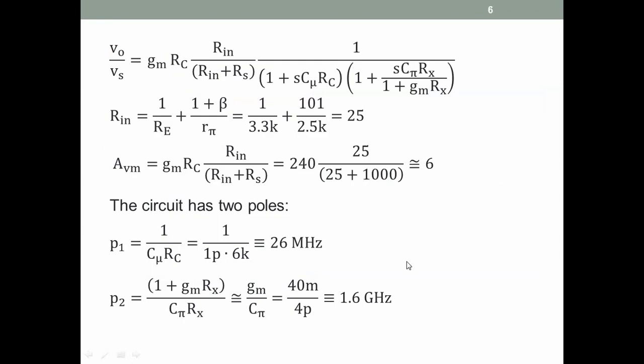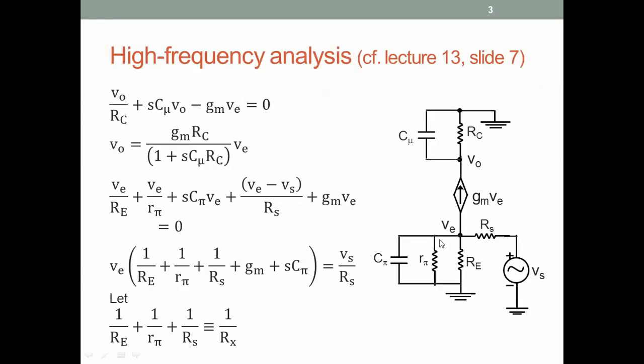So let's go back to the circuit. I mentioned this just a little while ago. There is no capacitance between the input and output of the common base amplifier because of the construction of the bipolar transistor, and because there is no Miller capacitor, there is no Miller effect experienced by the common base amplifier, and therefore the poles of the common base amplifier, the dominant pole, are at much higher frequencies compared to the common emitter amplifier.